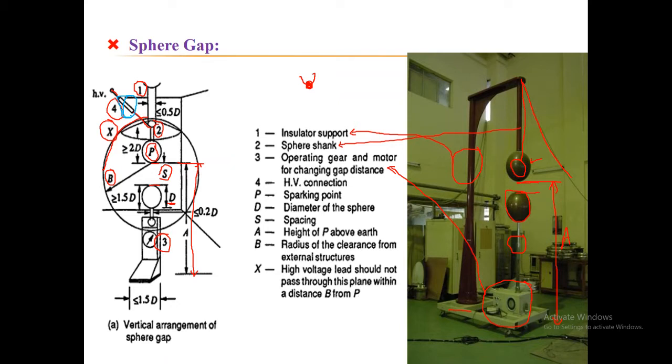Because if we increase the value of resistance, it reduces the peak magnitude of the generated impulse voltage. So for impulse voltage measurement the water filled resistor should be only a few ohms, but for DC or AC voltages it will be thousands of ohms.